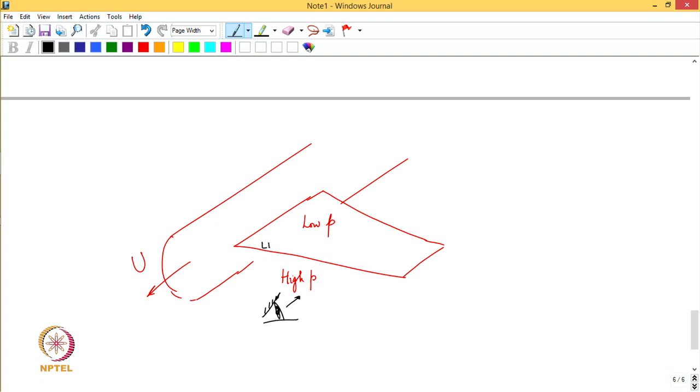This is the leading edge of this wing, so I am looking at this edge of the wing. What I see is that the pressure on the bottom is high and the pressure on the top is low, due to which flow at the bottom will actually try and leak to the top surface. So, what we will get are wing tip vortices.